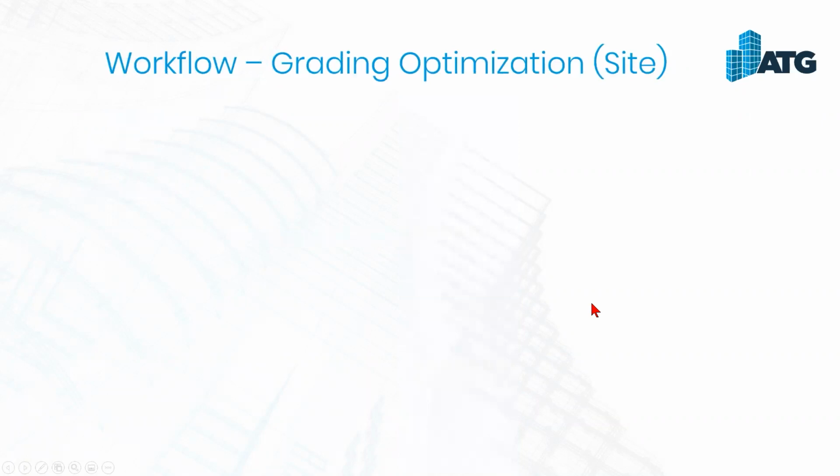Once we get through this, we'll be a bit inside of the software for the duration of the webinar. So number one, we need to define those site limits for our grading. So this might be our exact property line. We might offset that and come in for 5 feet.